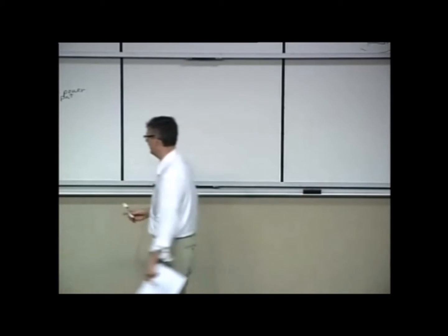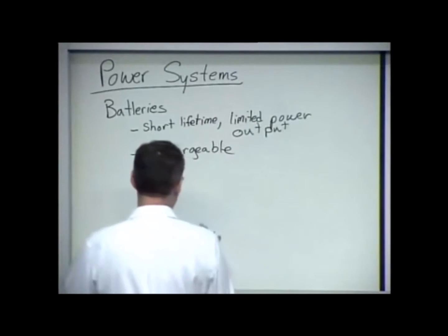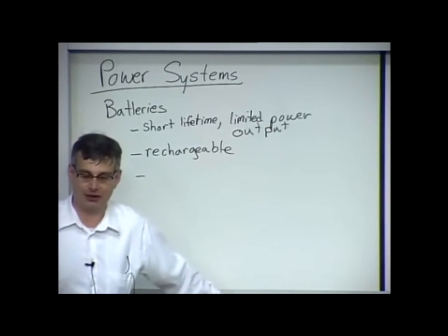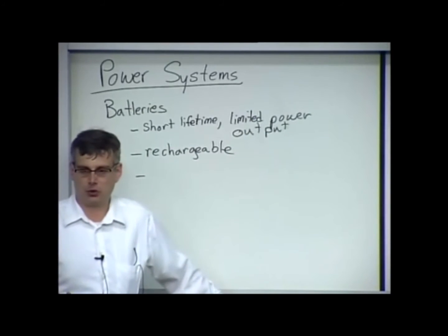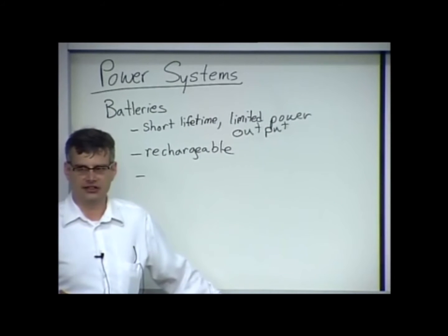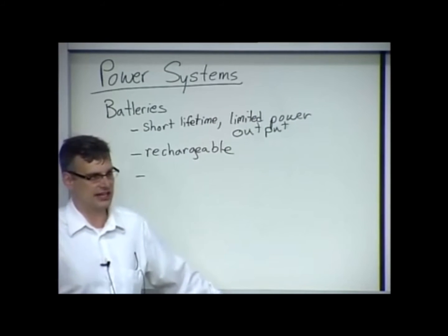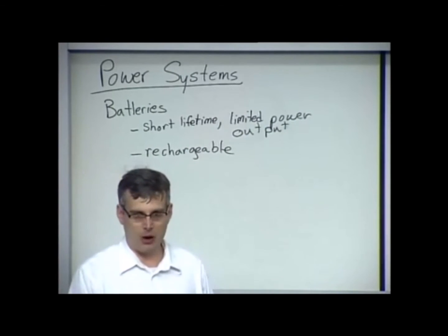And so because of that, and again, now you have this chicken and the egg problem. Oh, you said, well, I just got to add a thermal warmer to my battery to make sure it operates in space. Well, wait a second. How do you drive it? Do you drive it from the battery? No, you drive it from the solar cells. Well, what if you get in a shadow and you lose power for a few minutes?